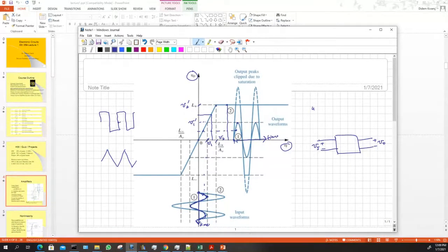Now, this is ideal because it goes like a straight line, perfectly linearly from the bottom to the top. It's pretty much ideal, other than the clipping. Let me explain the clipping. If your input voltage went up too high, what happens? During this time period, it goes above the maximum input that we were allowing to the system, and then the output just becomes flat across that top. So you'll see this cosine going up, then it's flat, and then going down.